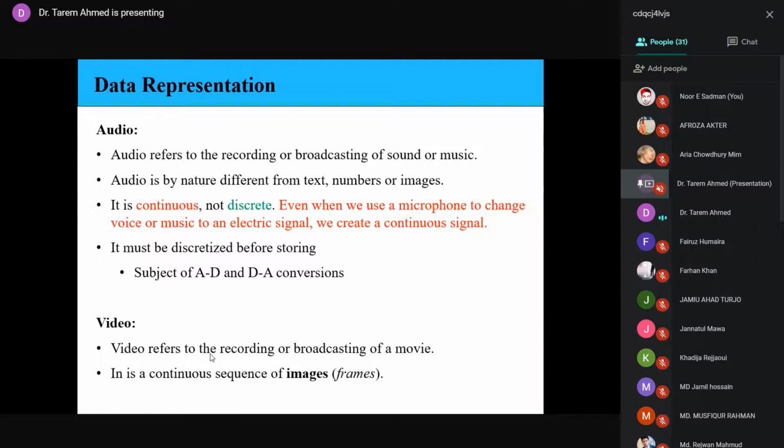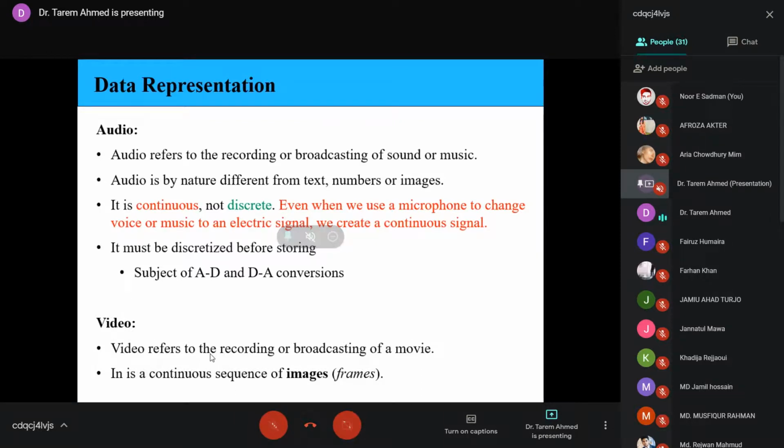And here also there are two kinds of compression: lossy compression and lossless compression. Lossless means the compression algorithm is exactly reversible. All the fidelity and detail can be recovered at the receiver. Lossy means you are doing some averaging at the transmitter, you are actually reducing the quality. You're taking 4 pixels together, averaging them out, and sending one value for 1 pixel instead of 4. This is done where the exact fidelity or image quality is not that important.